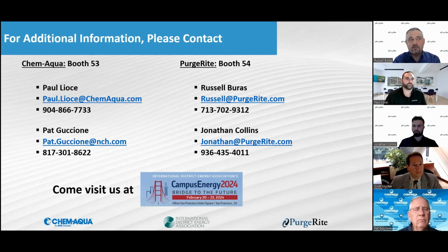And if the chemistry is the same, we can combine different types of pipes. So for example, we have been asked to flush, let's say a condenser water pipe that was just one direction, and there's a chilled water pipe. We can bump off those to another one. We've done heating water and chilled water piping at the same time by connecting them together.